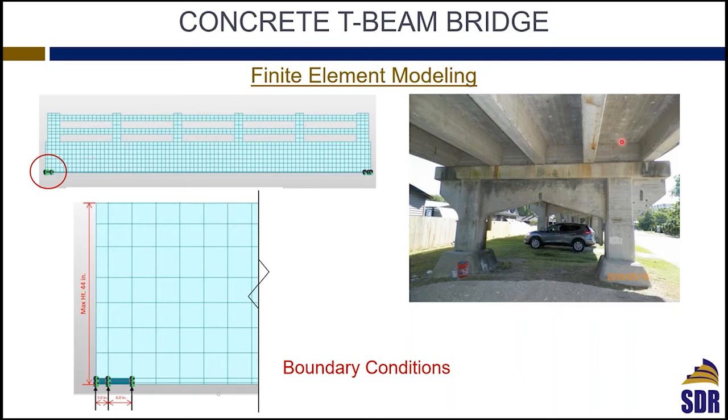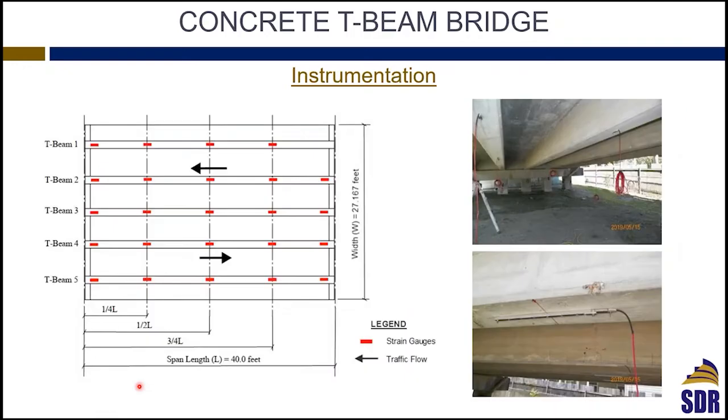Again, same thing. If you look, those beams are sitting on the pile bent or the bent cap, but again, they are not resting at one node. So I zoomed in to show you what the boundary condition is. You see, we had 9 inch of the beam sitting on the top of the bent cap, and that's why we are preventing the displacement of the nodes along the 9 inch of the beam.